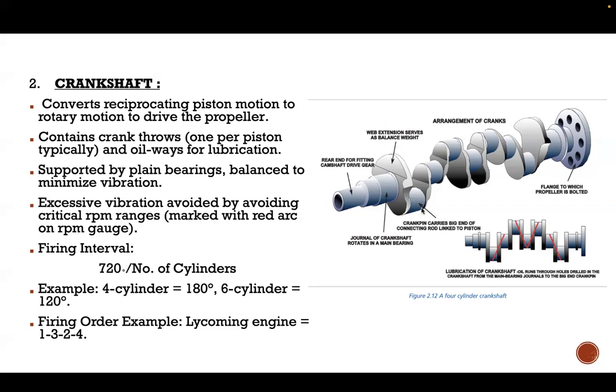You'll have bearings in it, which help us get that circular rotary motion without any loss of horsepower. But due to the friction of your bearings, if they're not well lubricated, we are going to have a loss of power that is called frictional horsepower. So you can have only some amount of the power given by your engine. We have to subtract it from your indicated horsepower to get your brake horsepower.